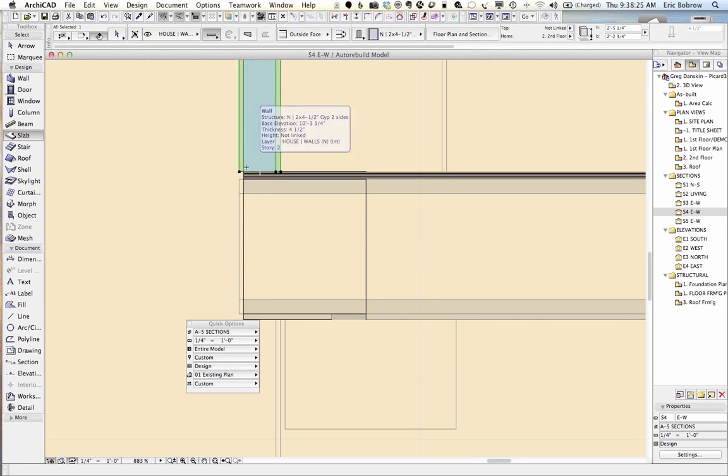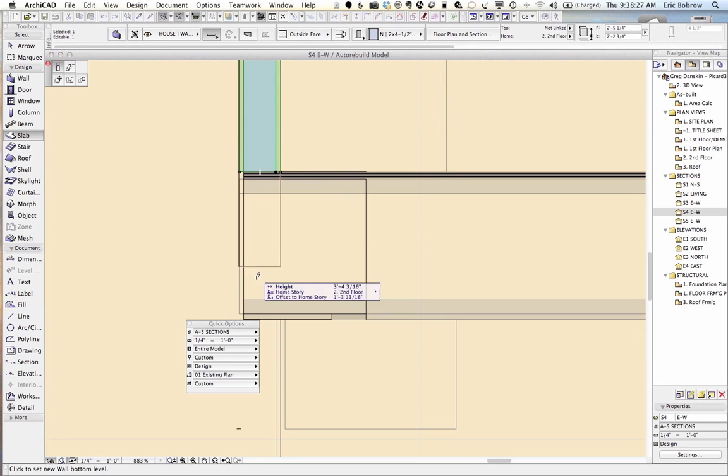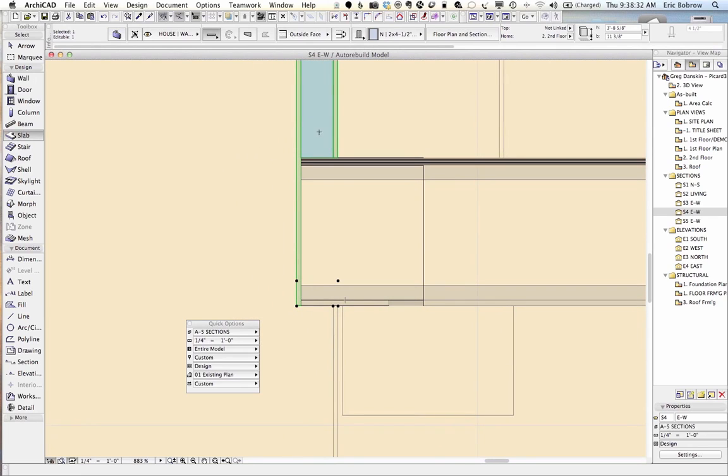And now if I select this and I stretch this down, you can see that the core of the wall stops on top of this core. The sheathing, the drywall comes down and terminates properly here. So is that? Yeah, that's exactly how it should look. Okay. The base then of that wall, or the starting height of that wall, changes then, right? That's right.